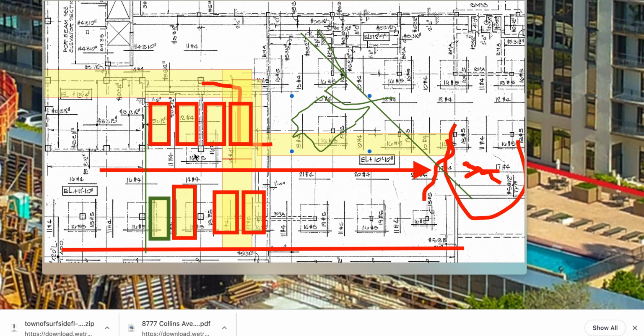Right to the column, and then back up. This one wants to back in. Comes right to this column, maybe, if the car's not present, and then backs up. Enough of that charging, enough loading and pounding right here starts fracturing around the columns. It all starts working on there. Plus the dead load is now working on it. No BMAs over here too. These cars come in, they want to get there, they come this way, maybe they charge it only here, but it stresses the column here.